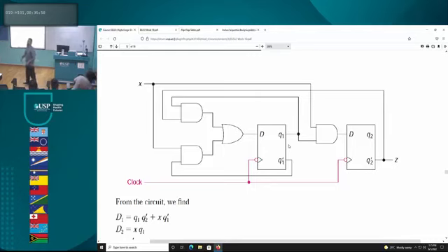When we say what is the state of flip-flop 1, or flip-flop C, or flip-flop K, or flip-flop D, it means what is that particular flip-flop storing in its memory at this point in time? And if somebody says, what is the Q, or what is the Q of D1 or D2? That means what bit is being stored now. What is the Q star of D1 or D2? That means what is the next state of that.